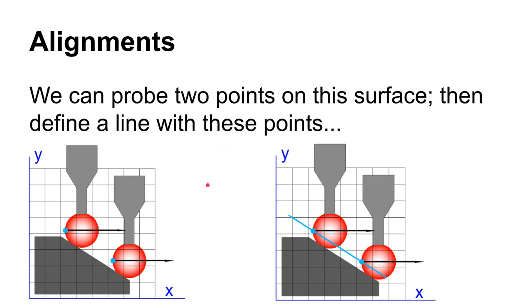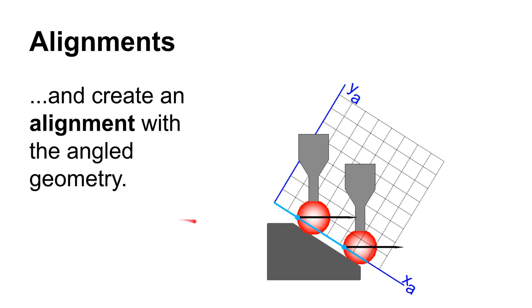All right, so what you can do is use this technique to actually build a whole reference frame that your part exists in. So one of the things that you do with GD&T is you set up different datums to establish a coordinate system. You establish what's called a datum reference frame. And once you have that datum reference frame, you can do things like talk about where the true position of a feature should be, and you can give it a position tolerance and tell it, the true position where this should lie is located at thus and so inside of this datum reference frame.